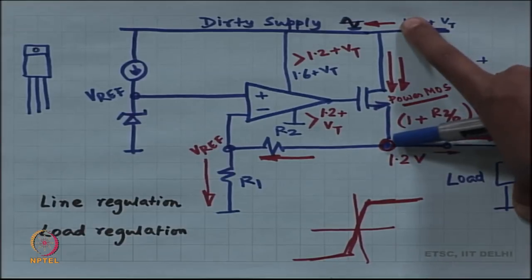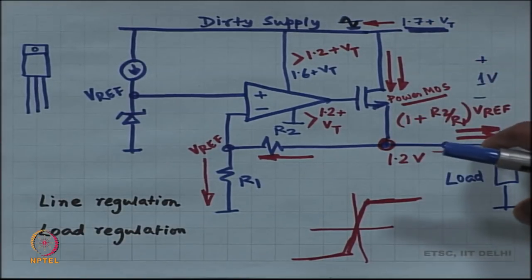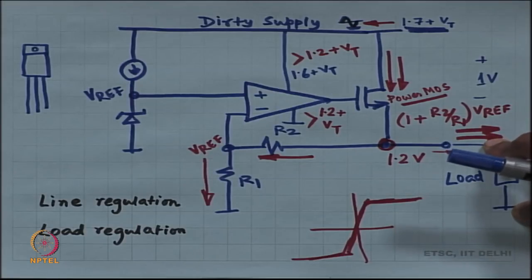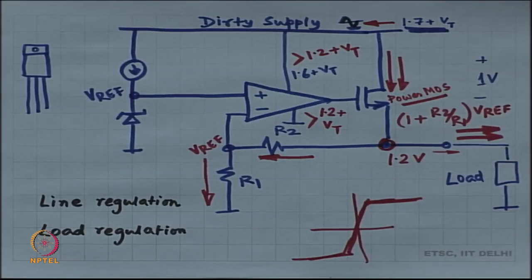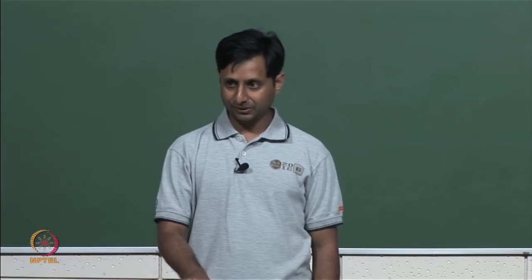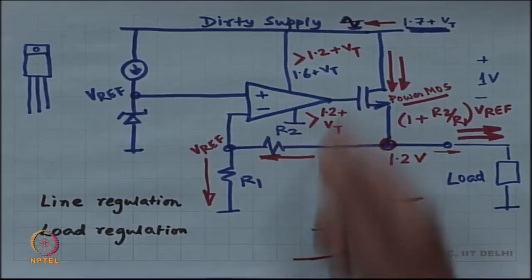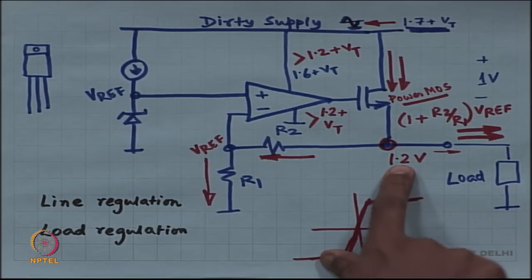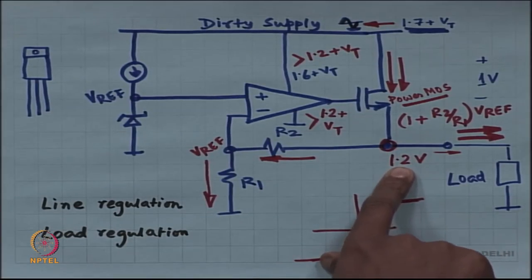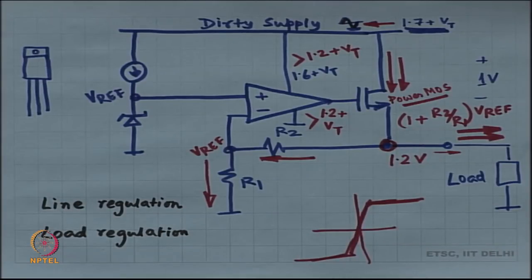So, out of an 11 volt supply you are delivering 10 volts, right, then suddenly your efficiency becomes 10 by 11, which is much better than 60 by 110. Okay. So, it all depends on how large this value is. If this value is large, then you are at an advantage. If this value is low, then unfortunately your efficiency is going to drop like a stone.